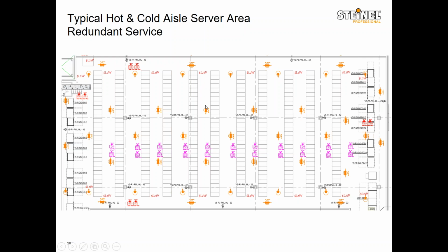Because it's isolated, we have the sensor with a door at either end. We have the sensor, instead of mounted at the very end looking in, mounted over here looking back towards the door. What this does is it gives us the ability to reduce one sensor out of the bill of materials for the same length of aisle.